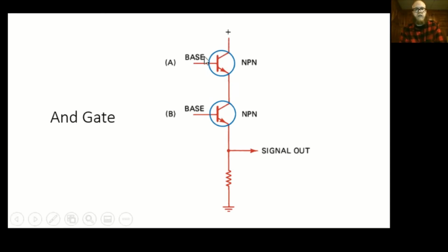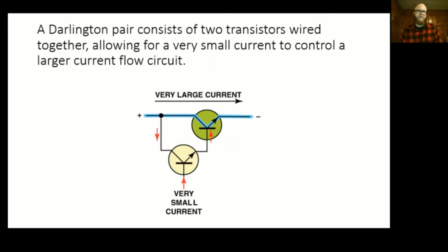So this has been turned on, and I would need my light sensor, maybe my photoresistor or maybe a photodiode, to then turn on when I had a dark enough atmosphere for my lights to turn on, right? Because we're not going to just turn on the headlights all the time. It's going to put drag on the charging system, which drags on the engine, which reduces fuel economy, and manufacturers are trying to produce as much fuel economy as physically possible.